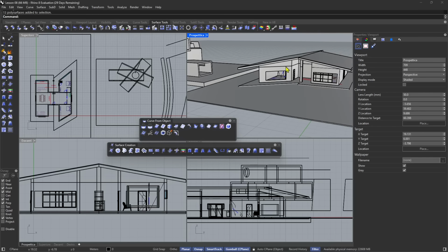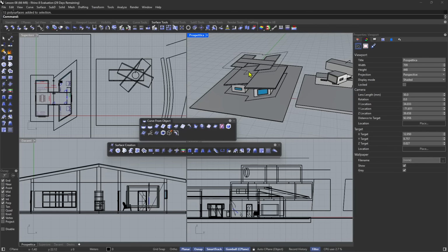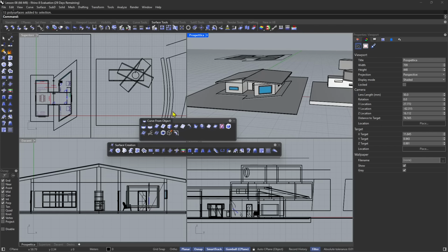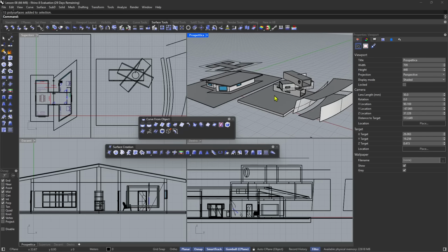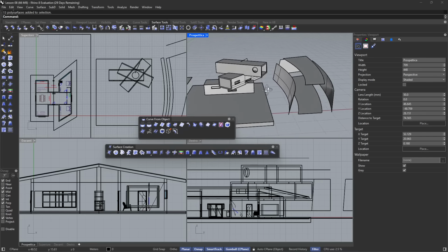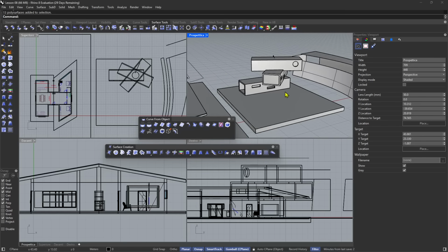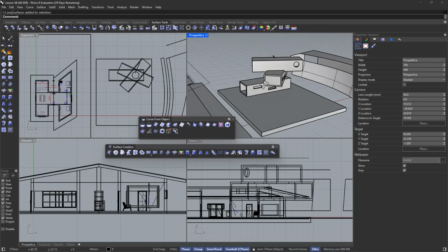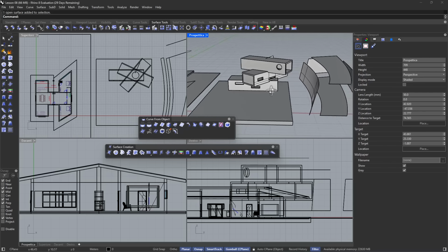I created here a roof, and also I can show you how you can do it by extracting lines and working with this menu right here, which is called the curve from object menu. And also we will use the surface creation toolbar. And here also a couple of examples of how we can create openings starting from the mass project that we did before. We can start to create openings and then again place panels and create frames and fixtures.